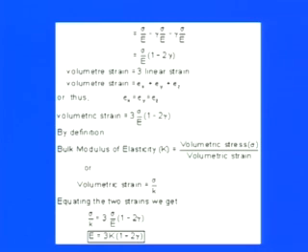So, we can see here that we can easily relate those components if we know the exact relationship: what kind of material is there, how these stresses are being formed, and what kind of strain components are there. In this case we also discussed that if we have gamma, the shear strain, at 50%, the half, then the K value is infinite. That means the bulk modulus is infinite, or the material is highly incompressible. So, that is what we discussed.